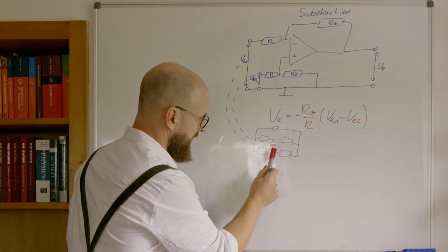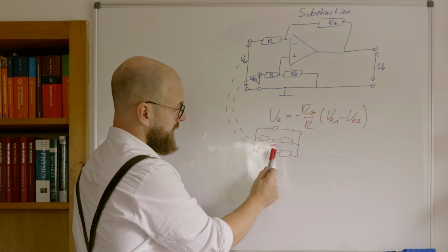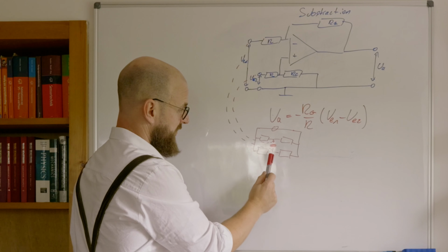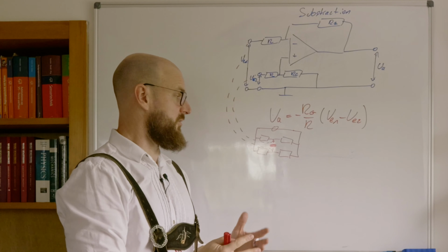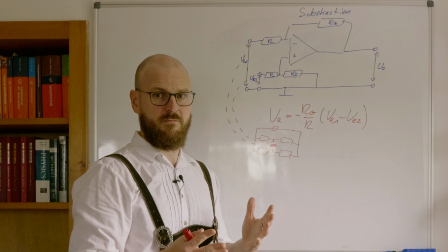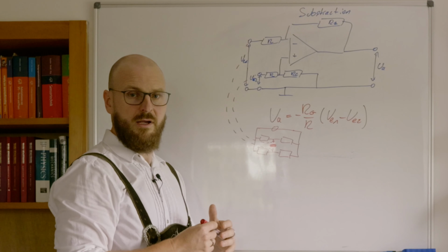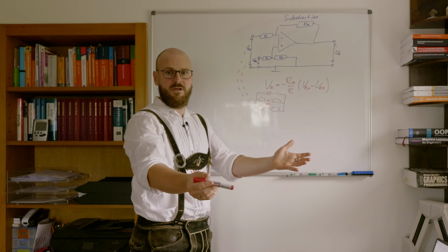And now connecting that side of our bridge would ground the bridge in that place. So we would change the electrical circuit of our measurement bridge drastically. We can't do that. We just cannot introduce a ground within any existing electrical circuit.